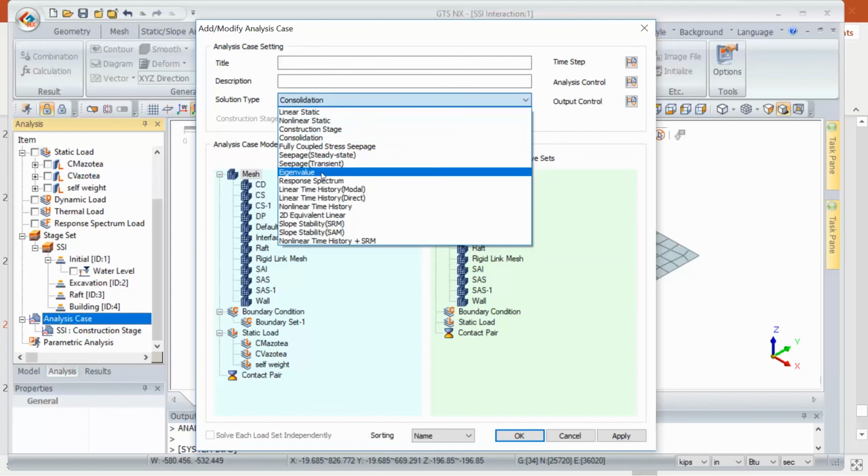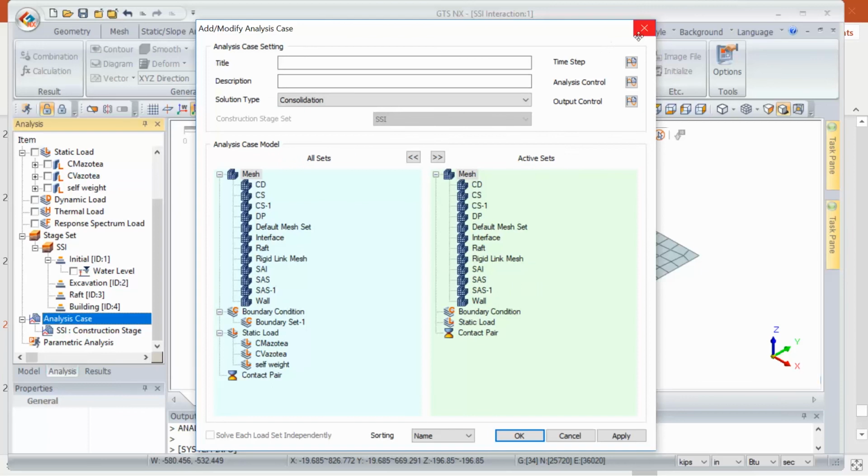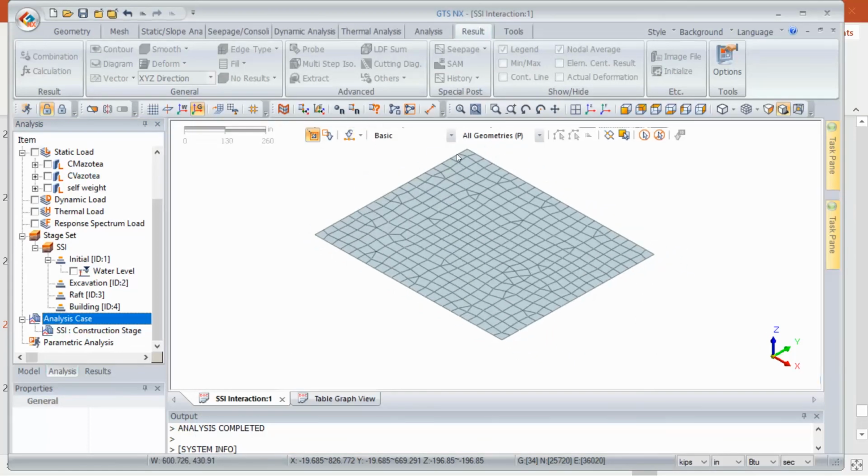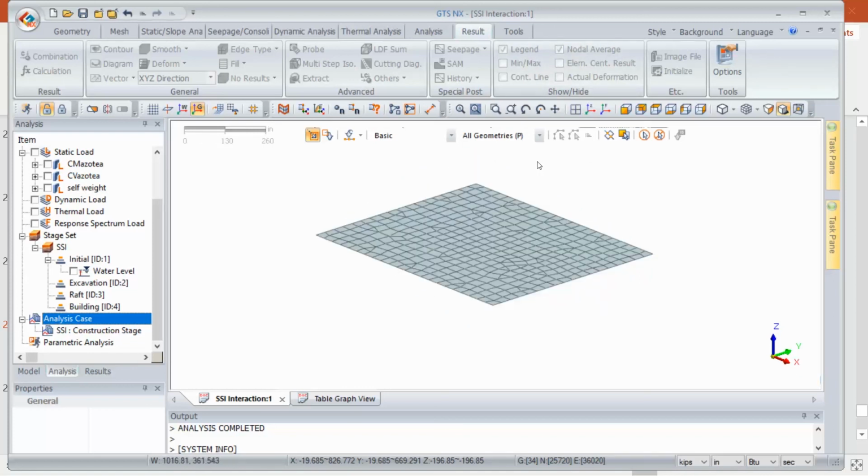as well as some sort of vibration analysis, eigenvalue, response spectrum analysis, or our seismic analysis, or time history analysis. So all this is possible with the structure and the terrain itself, and we would be getting a lot more approximation or better results for those kinds of soil structure interaction analyses than we could ever do with the spring elements.